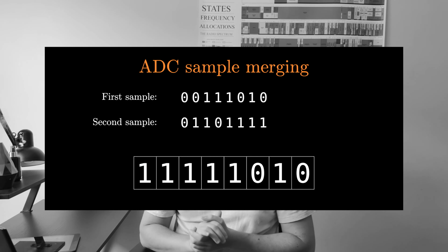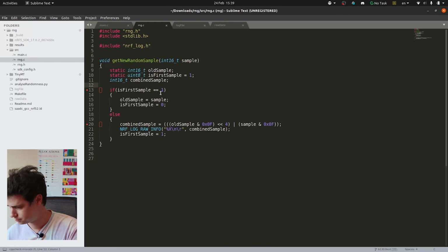Before that, we saw that we had up to 5 bits of randomness inside of our byte, so we're just taking the 4 lowest bits. Hopefully the 4 lowest are the most random ones among the 8, and we take 2 of them, sticking them together to make a full byte. That's what this small contraption is doing.